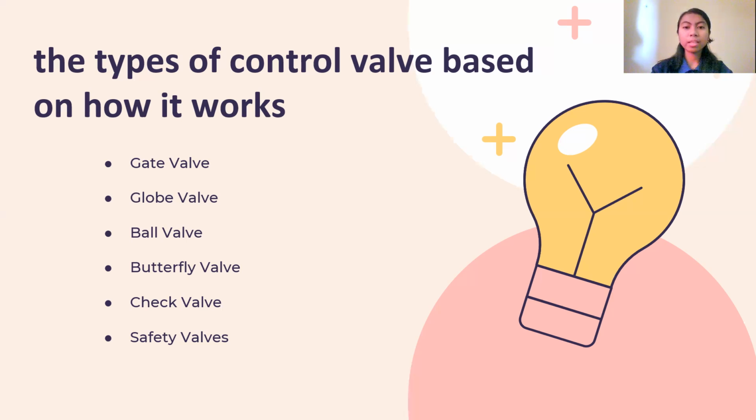It is connected to a stem that connects to an actuator or handle on the outside of the valve. In the closed position, the disc is perpendicular to the flow, as shown in the figure, and is held by a valve seat. The stem is also sealed using an O-ring.